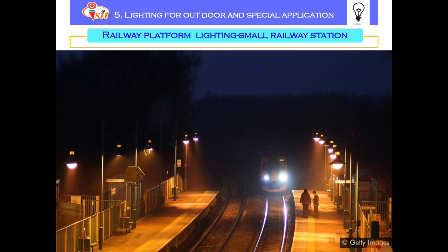For the lighting system, tubular steel poles support lighting luminaires. The lamps used over the steel poles may be fluorescent tube, high pressure mercury vapor lamp, or low pressure sodium vapor lamps. The distance between two poles is 10 meters. The poles have brackets bent towards the platform surface with a shade which diverts the light towards the platform. At the starting and terminal poles, the lamps are brighter. Therefore, large wattage lamps are used at the starting of the platform and at the terminal poles. The light is concentrated towards the platform and also diverted on the rails from both sides of the platform poles.